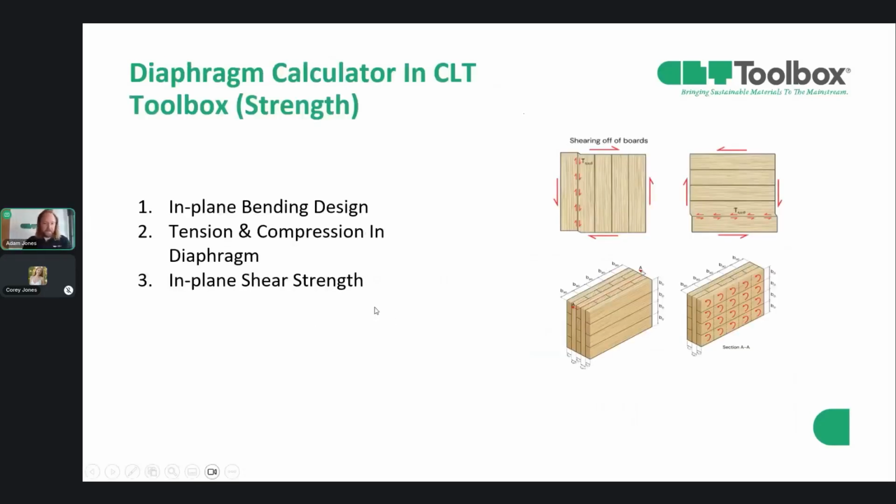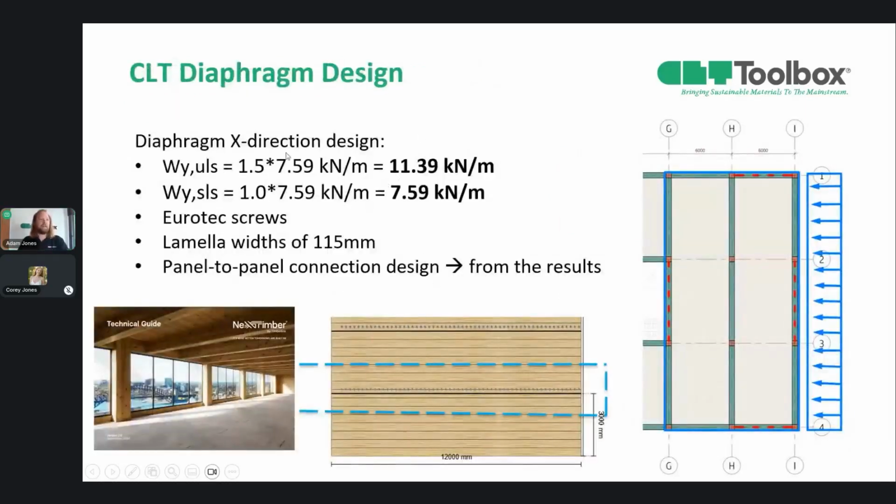When it comes to the in-plane strength of the actual diaphragm, there'll be 3 checks. So the in-plane bending design of the overall diaphragm, a tension and compression check with the girder analogy, and then the in-plane shear strength with the 3 failure mechanisms. All right, so with that said, that I think is important context for the diaphragm, which will hopefully let you follow along a little bit closer when I take you through the story of the design.